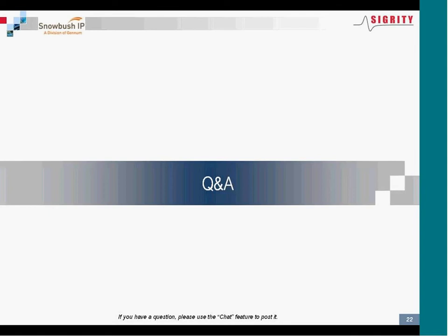And just to confirm, if someone has a model that has the back channel capability implemented, but they want it to run just as a pure IBIS model, they could turn that functionality off. Is that right? Yeah, that's correct, and that's the way the Snowbush models work. You have the ability to turn the back channel training off, and they operate just as a standard IBIS 5.0 compliant IBIS AMI model. So again, the intent is not to exclude vendors or force customers to use a particular tool or anything else. There was just no other means by which to do this back channel capability initially.